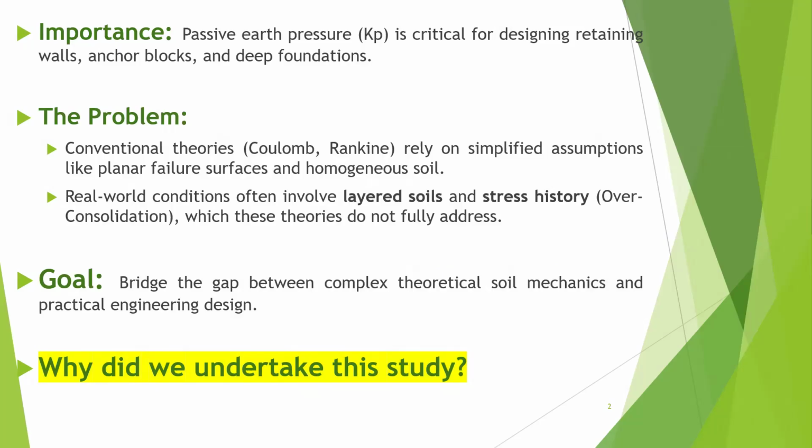They assume the soil is uniform and often ignore stress history. In reality, we deal with layered soils and over-consolidated sands. Our goal was to create a tool that accounts for these complexities while remaining easy to use in daily design practice.